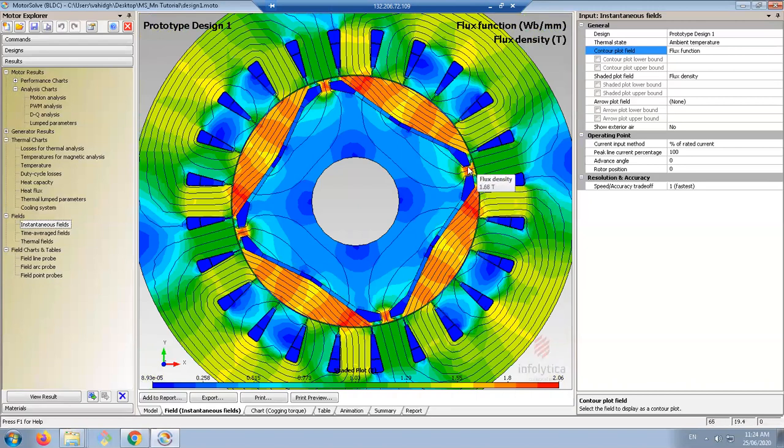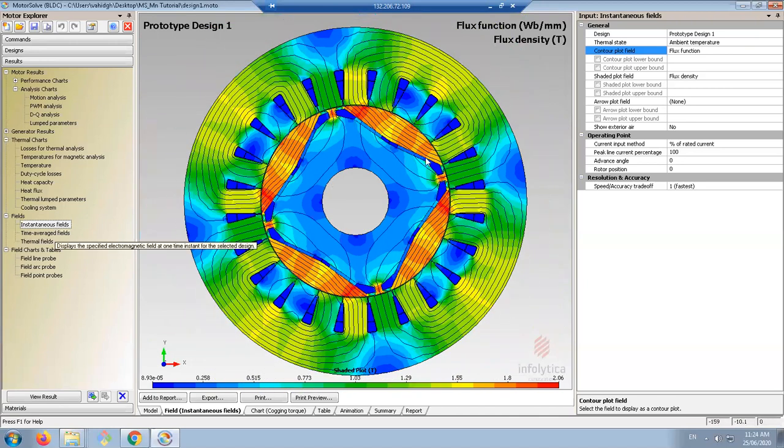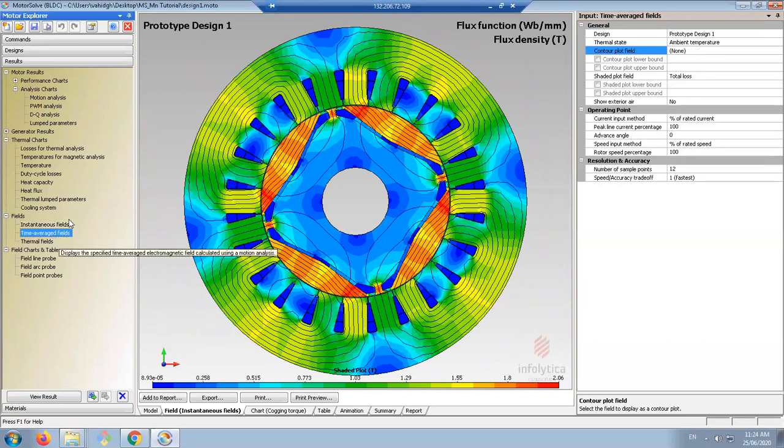You see the flux does not even go through the rotor back iron, meaning that this part is totally useless and wastes the weight of the mass of the rotor. If you don't really pass the flux through the rotor back iron, why do we even need to add that back iron to the motor? So you can definitely remove this part and reduce it, but to be honest, 1.94 is very bad, not acceptable at all.